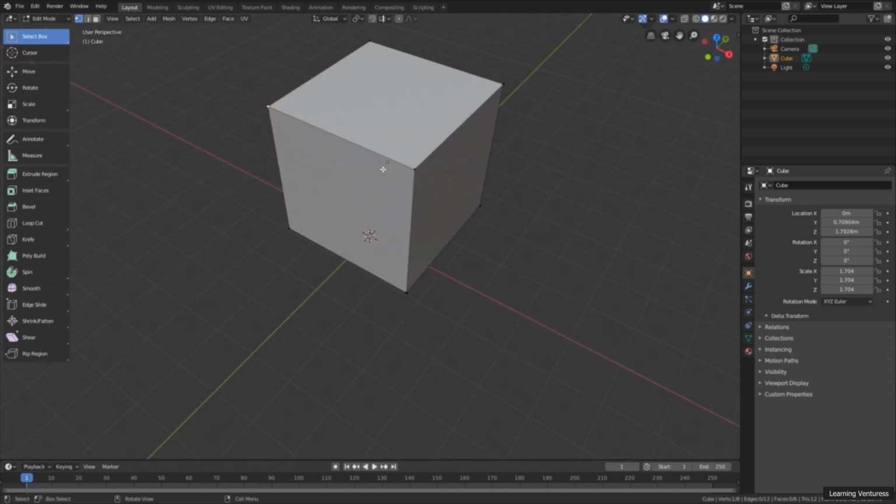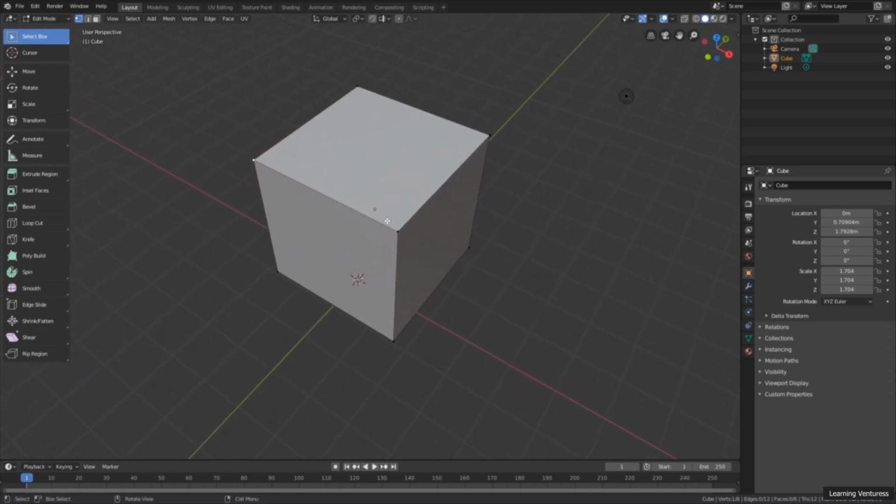We can click on each vertex individually to select them. We can add new vertex to the selection by holding down the Shift key. We can click on a free place in the 3D view to clear the selection. And we can create selection windows to select vertex groups.